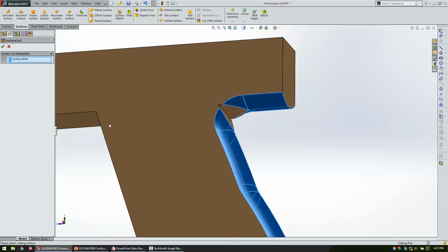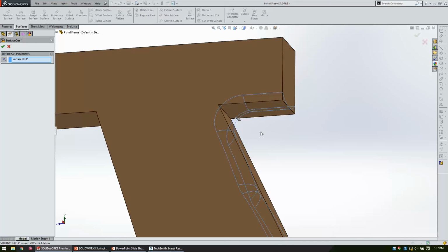The only time I've really had issues with this is where the surface did not fully split the solid model. If you're 1/1000th off somewhere in one corner, it'll absolutely freak out on you. So if you're ever cutting with surface, make sure your surface is totally covering your solid bodies. And I've personally never had an issue with it, but I've not done anything super complex with it either.